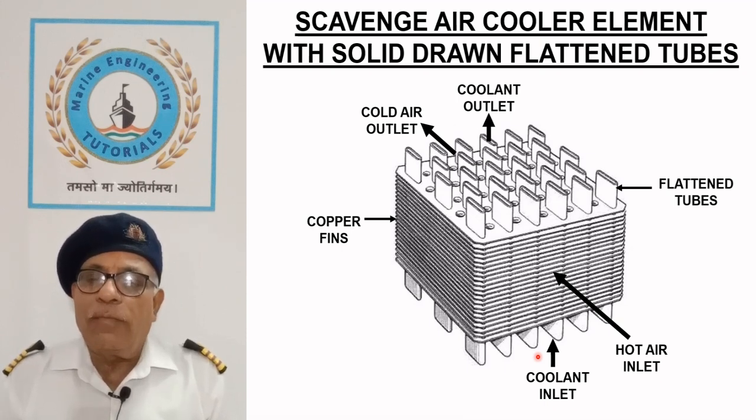Cooling of the air results in precipitation of moisture, which is removed by water eliminators fitted at the air outlet site. A change of direction is used to assist water removal. Condensate is removed by a drain connection beneath the moisture eliminator.